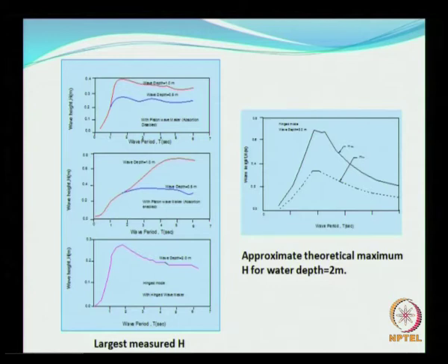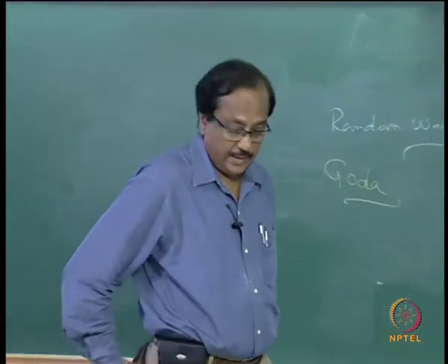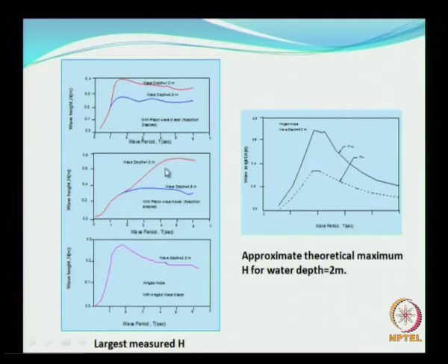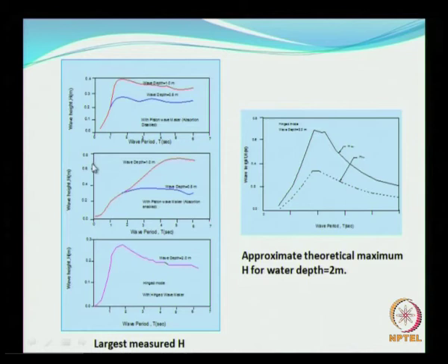So before this, continuing with the 2-meter wave flume, we also have what is called the maximum wave height that could be generated in the flume, which is limited by your wave period. As you see, if the wave period is higher, the wave height that could be generated will be higher, okay. As you see here, it is around 6.7 meters here. For example, the red one is for 1 meter water depth, and the blue one is for about 0.5 meters.